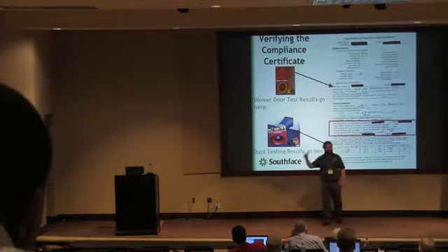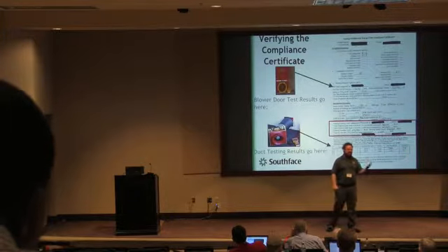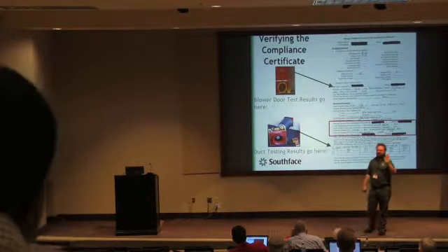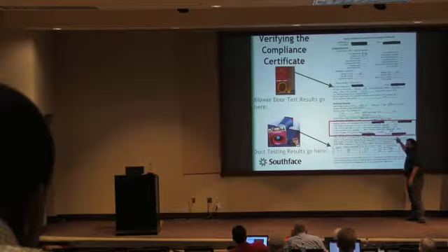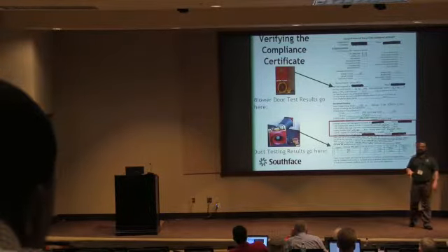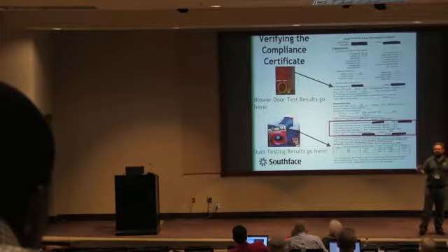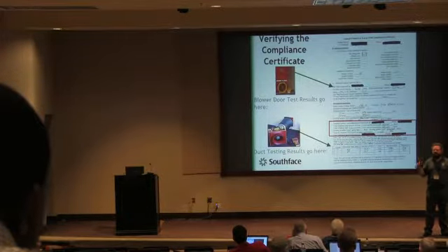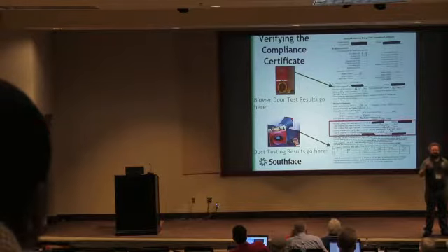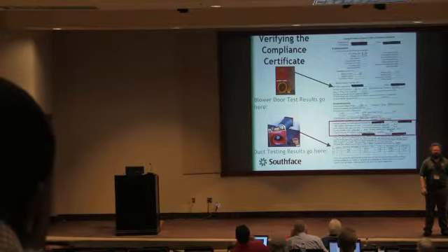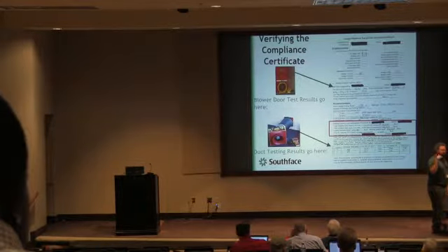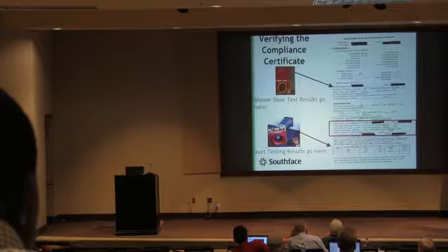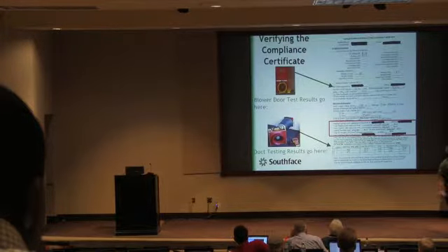Now, if I'm a really thorough code official, I'm getting the mechanical contractor to provide me with a summary sheet from their load calculation, and then I'm going to compare that to what's on the certificate, and compare that to what's installed in the house. All the information is there if you wanted to do it. I'm going to tell you that's probably one of the most commonly ignored requirements of our energy code, because it's a mystery to a lot of people. I think code inspectors out there a lot of times aren't catching people either doing bad documentation or, quite frankly, not doing any documentation at all on HVAC load calculations.